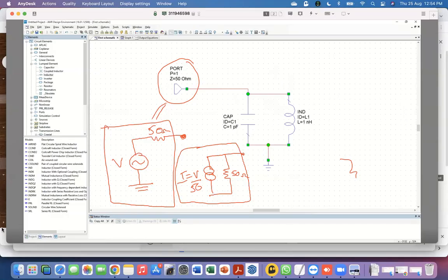The way you have to think about the detection part, remember that this particular point and this particular point, if there is no voltage, actually have no resistance between them. So the return signal, or if you're measuring something about the circuit, is the voltage dropped across this 50 ohm resistor.